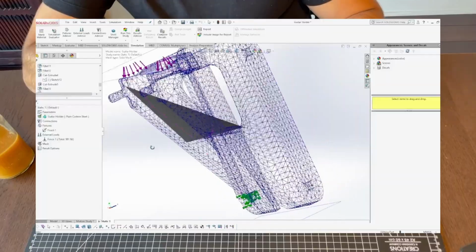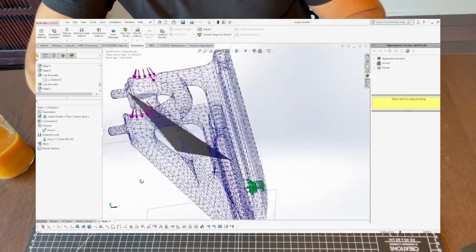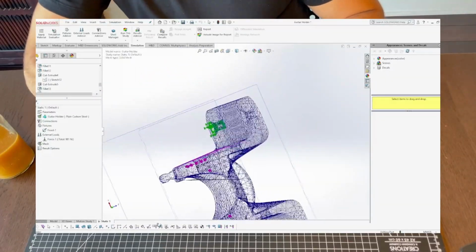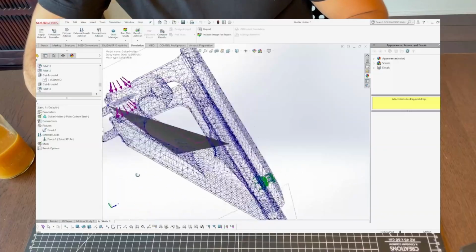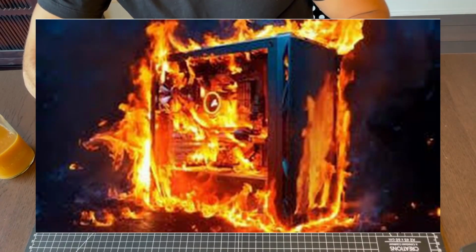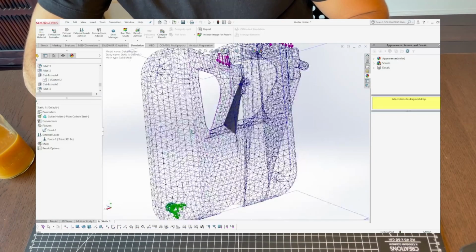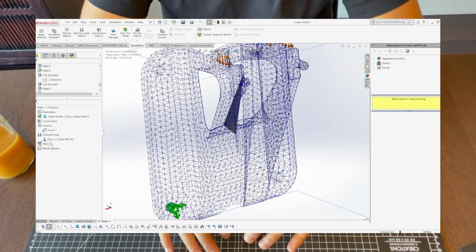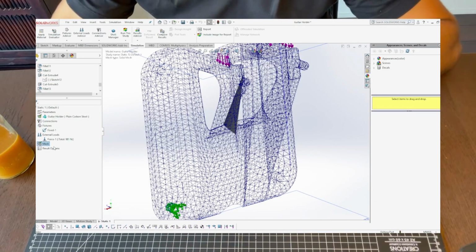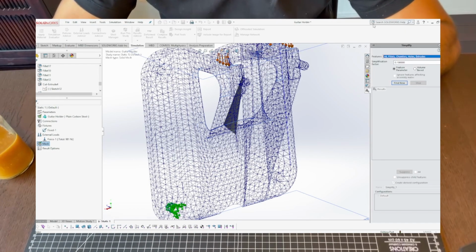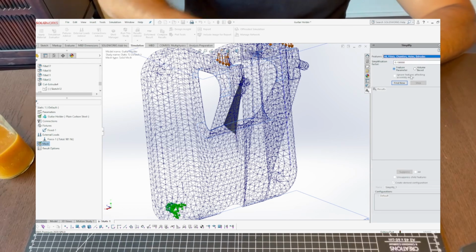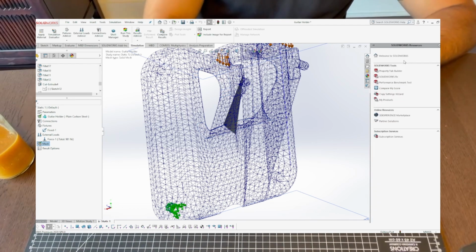I want the smallest possible size so that it captures all the information, but I don't want my computer to crash and possibly melt parts of it away. So my approach was to find the smallest geometry feature that I cared about in the part itself, and then make sure that it was represented in the mesh by defining the mesh size that way.